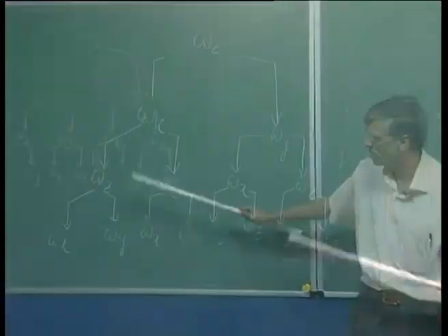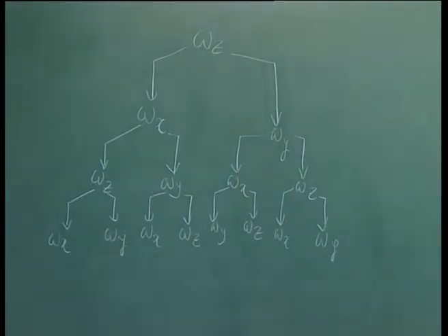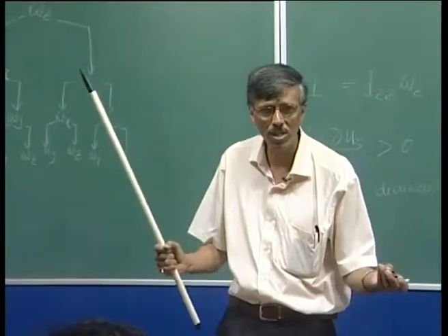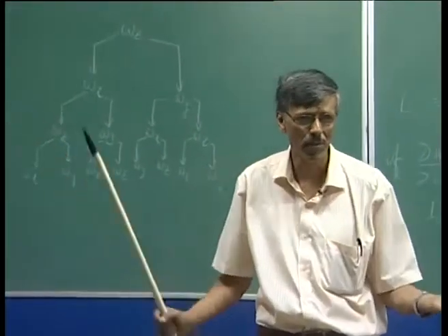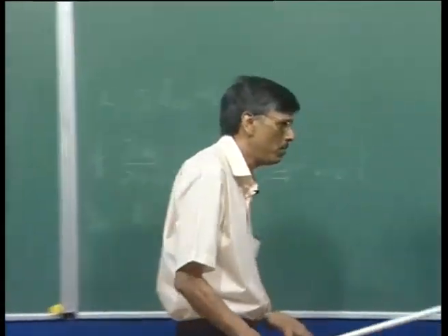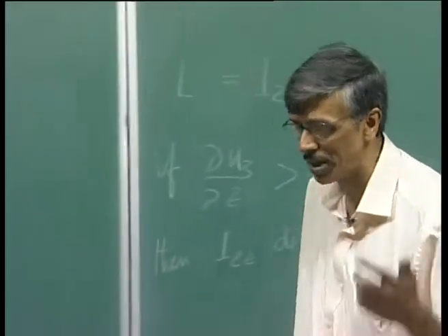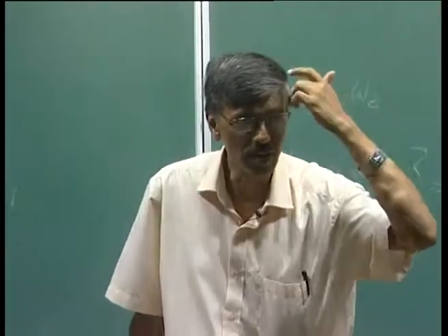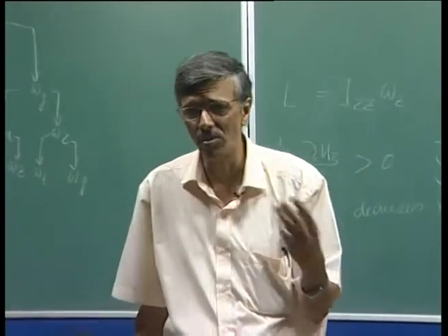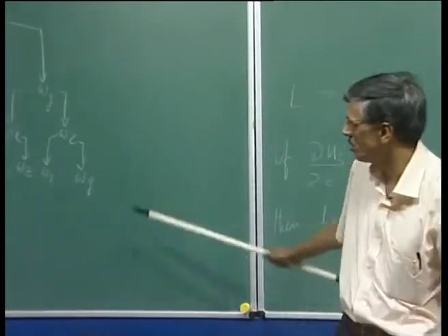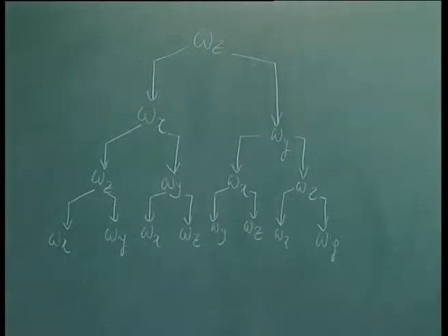So, what happens is this keeps on happening going down the tree. You are going to see smaller and smaller changes, but they are going to be isotropic, right. So, this isotropic behavior of vortex stretching also is used in turbulence modeling when one does large eddy simulation. There, if you are looking at the vorticity at the smaller scales, they are going to be as isotropic as it is indicated here.